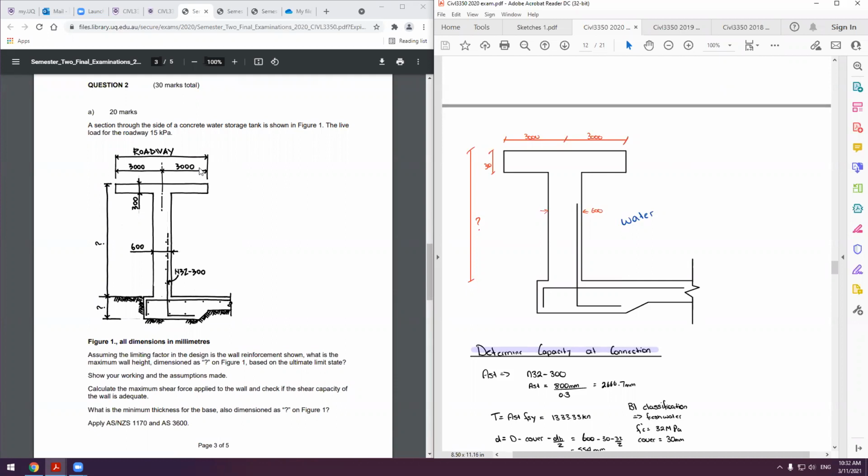One of the most annoying parts of this question is trying to work out where the water is, because he never actually tells you. It's on the side where he has written the reinforcement. I have learned that, so it's here. I can also tell you it's here just from experience designing water retaining structures. Wherever your slab is, it's going to retain water. Don't stress about that in your exam. If you assume the water on the wrong side, it's not critical. It's just annoying.